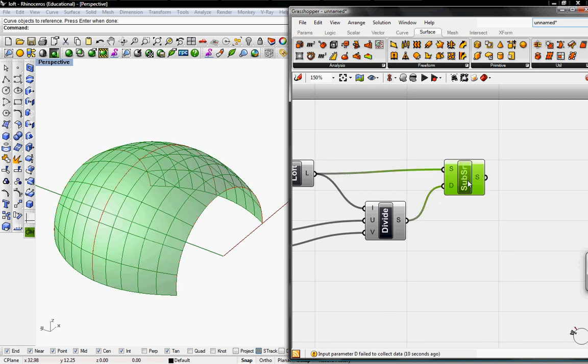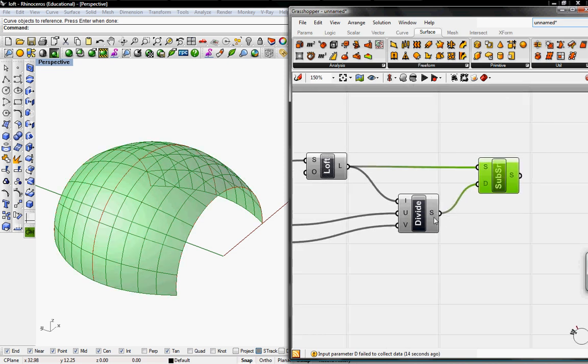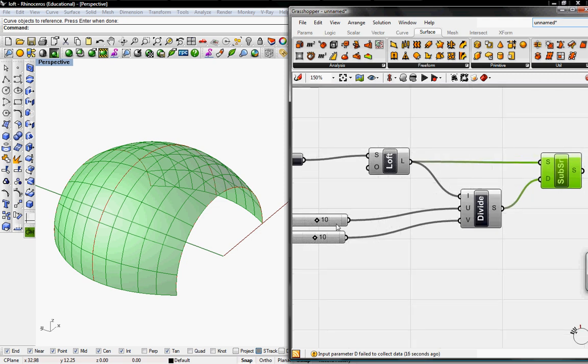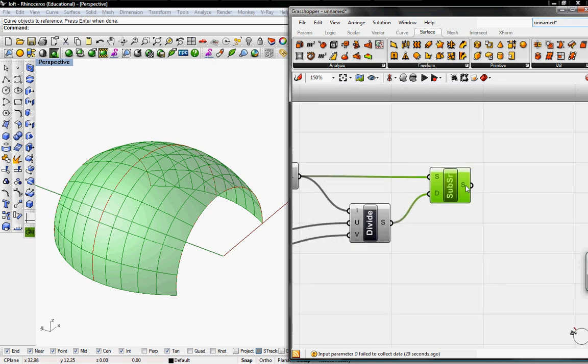And here our subsurface is now 100 panels based on our original surface, since we defined 10 in the U and 10 in the V. So it'll give us 100 panels. Next thing we want to do is to either manipulate per panel, or manipulate the vertices of each panel, or the edge, or even the point that the panels is located on.